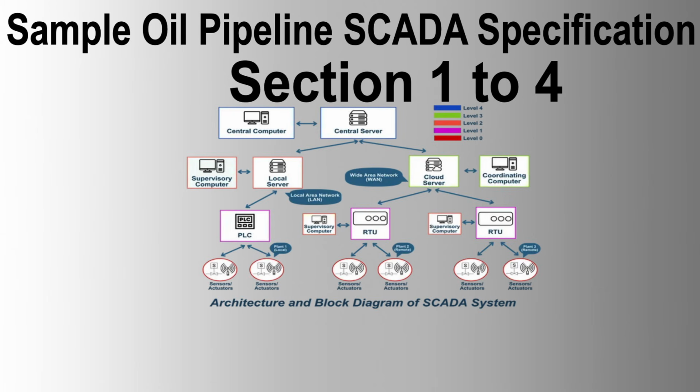Section 4. Specific Functional Requirements. 4.1 Start-End of Production Day. The SCADA Master Station shall operate under a concept of a start and end of production day, configurable designated time within the Master Station setup. This designated time shall be the reference for all equipment and software throughout the SCADA system.